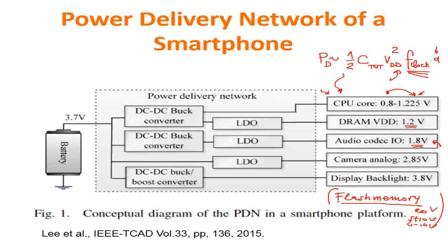Okay, but as you can see, this is pretty complex. You need a DC-DC buck converter in order to go from 3.7 to about 1, and then you also need it to be controlled by the operating system, because it's the operating system that knows at the low level when you can go slower with the CPU, and then can adjust the conversion factor of the DC-DC buck converter.